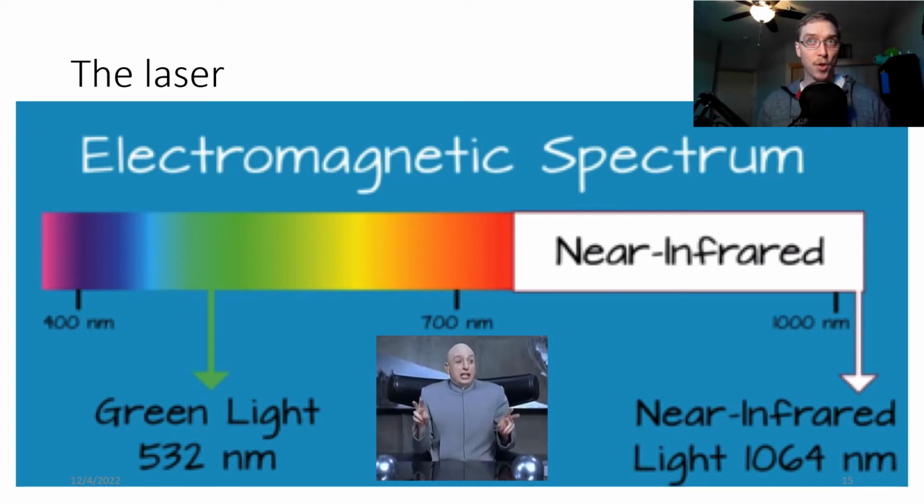If you're using a terrestrial or aerial system, basically that entire signal is going to be absorbed by the water, and you're not going to get anything back. So you lose that signal whenever you're over water, because water is really good at absorbing that wavelength. If you use a green light, you're going to be able to penetrate down through the water column and actually see the surface below. So you just have to understand what you're going for. If you're going for a prairie or a forest or a beach, you just have to make sure that the LiDAR you're using is one that's going to give you the return that you need. If you're trying to look at subsurface data over a lake, you're not going to get it with a near-infrared laser system. You need that green light system.